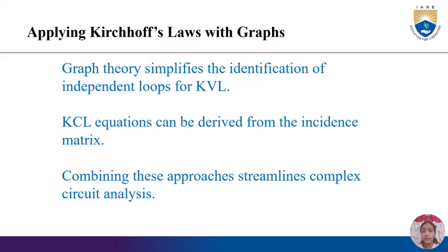Applying Kirchhoff laws with graphs. Graph theory simplifies the identification of independent loops for KVL. KCL equations can be derived from the incidence matrix. Combining these approaches streamlines complex circuit analysis.